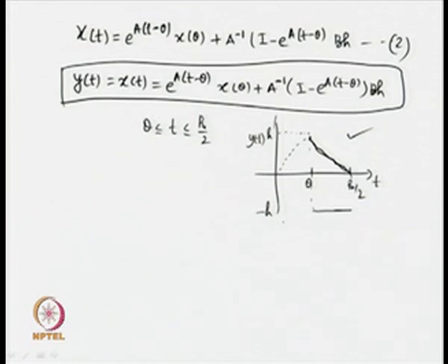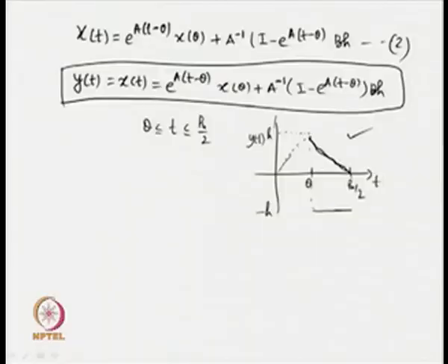So, if it is possible to obtain explicit expressions for different parts of the output signal, then it is also possible to correlate the parameters of the first order plus dead time model with that of the output signal. So, the measurements made on the output signal can be translated into the model transfer function form, because there is direct correspondence between the two.